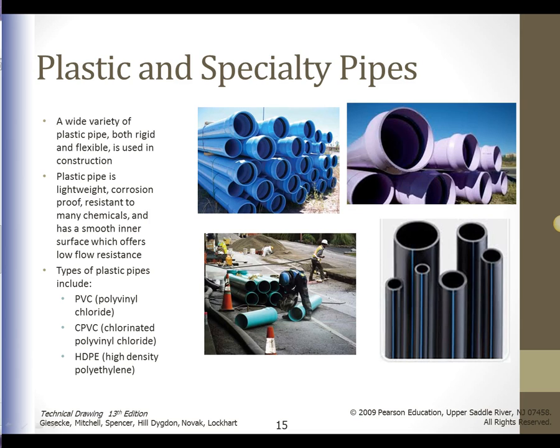There are various standards. The PVC and the CPVC pipe range from 1/2 inch to 4 inches in size. And the CPVC pipe is similar to the PVC pipe, but the CPVC has a much higher temperature rating. The application of these materials varies according to their physical properties and temperature.